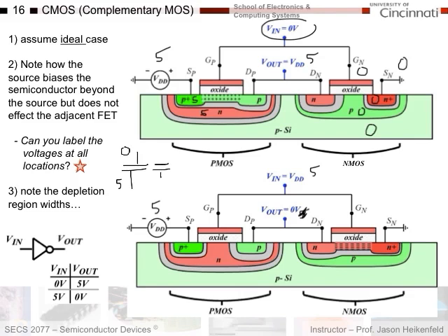Well, isn't that the exact same thing in terms of voltage drop as having 0 volts on this side and minus 5 volts here? Because in both of these, I still have the same net voltage drop. All I did was subtract 5 from both sides, and I get minus 5 and 0. So subtract 5, I get the same net voltage drop.